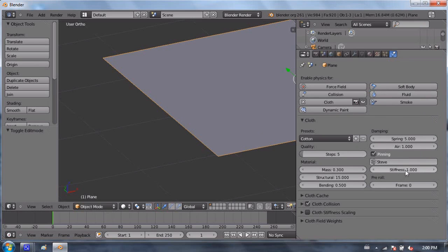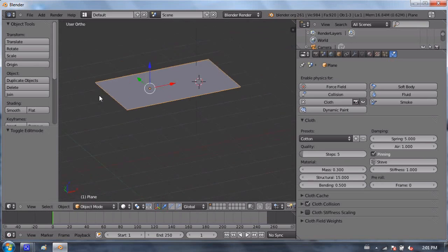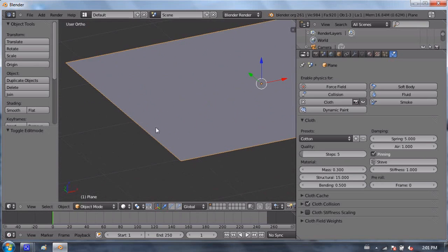And maybe you'll look under it, and you'll find a stiffness number. Stiffness can be 0 all the way to 1 or anywhere in between. And what stiffness means is how pinned it is, how solid or how stiff that pinning is. If it's at 1, that means it's going to stay exactly where it is as long as the cloth isn't pulled away from that point by some external force, like some cloth or some vertex pinned to something else that's pulling it away. Which gets kind of complicated, but that's okay.